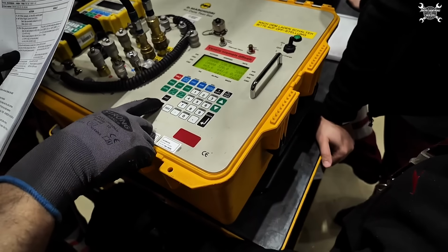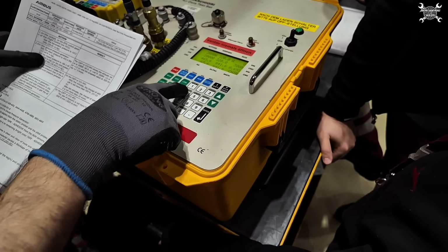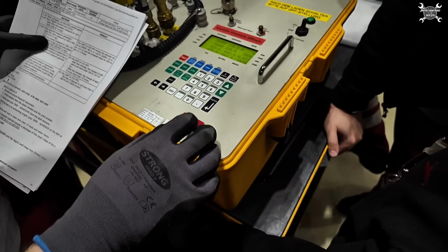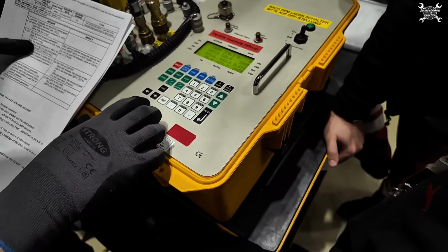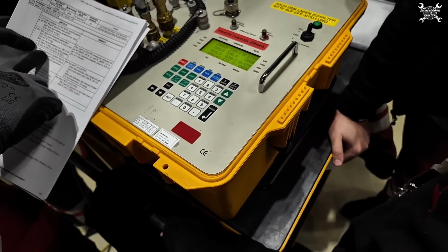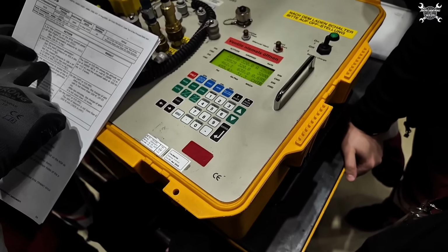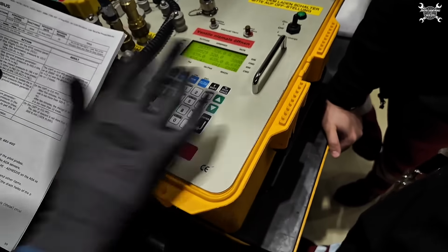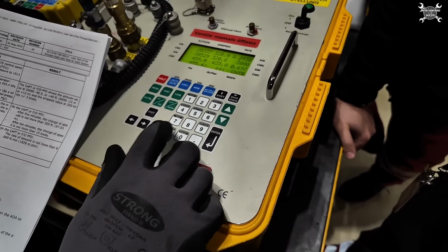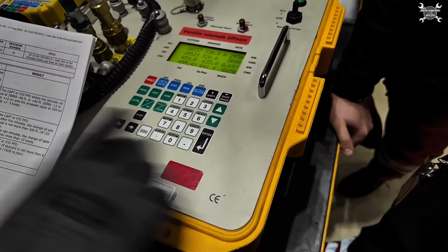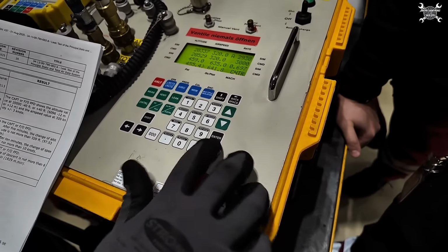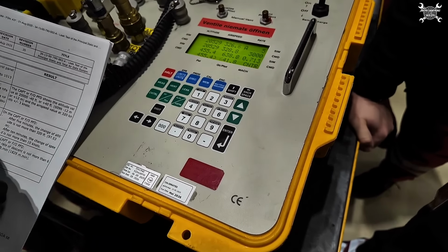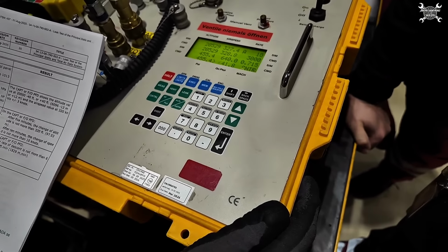And now we'll go here and we'll put this one 455.4. Okay, enter. And for the other one, it will be 641.8. This is for the speed, the total pressure. Static pressure is the altitude, and total pressure is the speed.